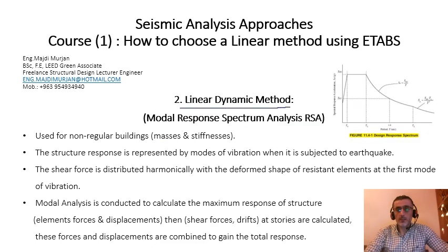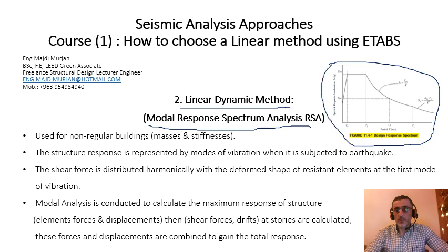Now let's talk about this linear dynamic method, modal response spectrum analysis. As we see in this figure, we can see this spectrum, different accelerations for different time periods. This spectrum was formed for different buildings under different shakings in different areas in the United States of America.